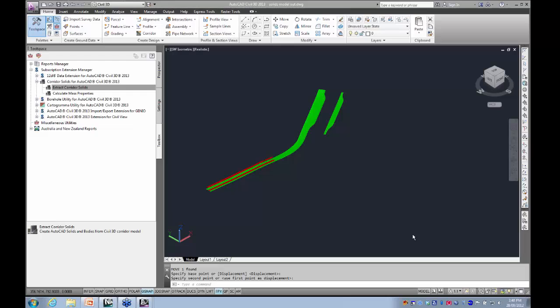I haven't tried the 12D drainage, but you can certainly use the 12D tool to import your 12D model into Civil3D. You can then reproduce the corridor. We don't actually get the corridor from 12D, but we can certainly reproduce it using string lines as a Civil3D model, then take it into Navisworks. So that's how we do that. Just as a question that was asked there.